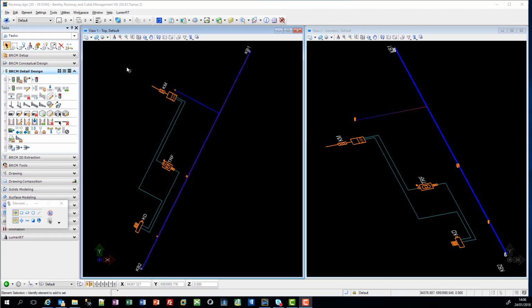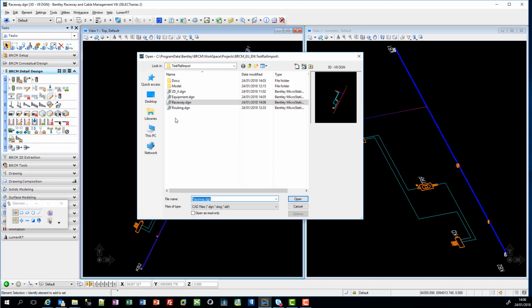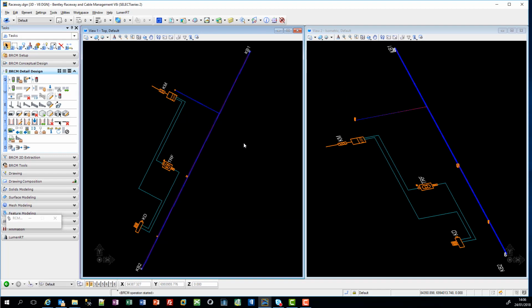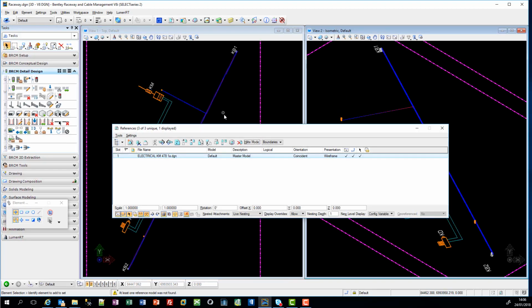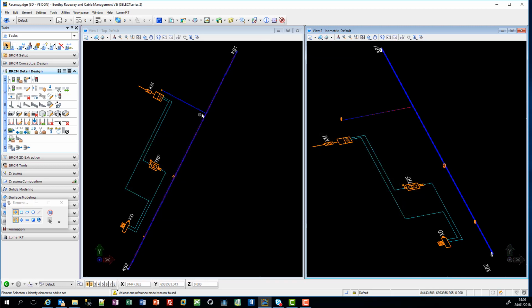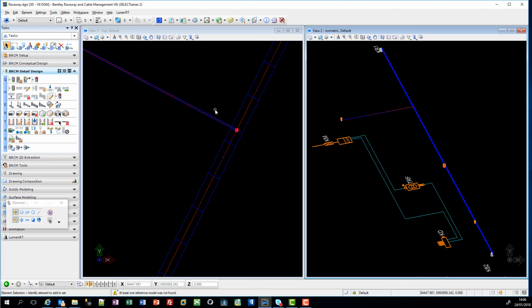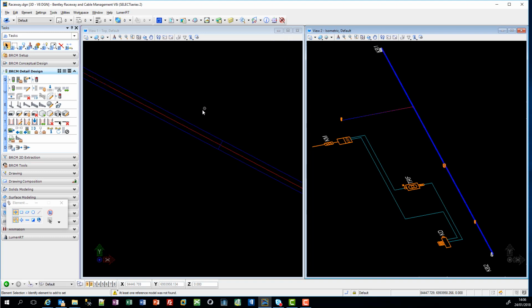I continue here in a separate drawing, the Raceway drawing. So here I selected the Raceway drawing, and in the Raceway drawing also the file from Promis.e is attached as reference file. And here it is possible to select lines, for example, from that conduit here, and to convert that line into Raceway systems or conduit again.